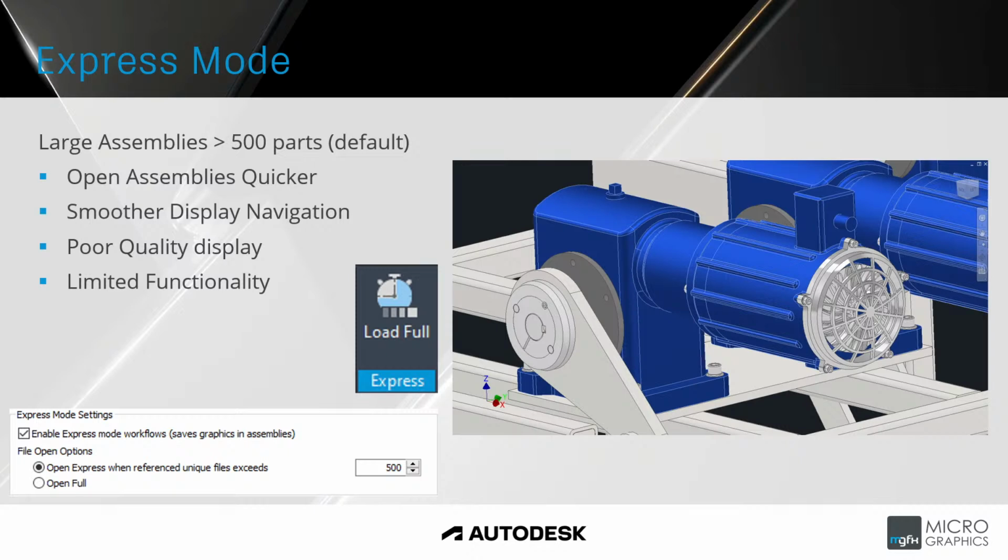So Express mode, essentially when opening up assemblies, improves the opening time. If you do need to work within the assembly and have all your functionality, you would click load full, and it would then take the extra time to load the complete assembly with all of the functionality.